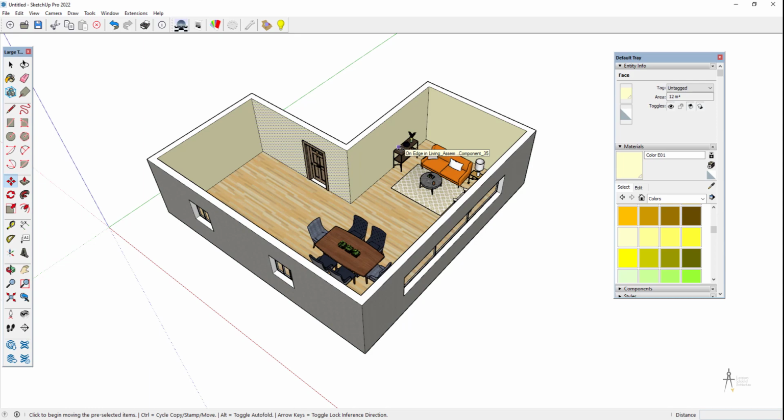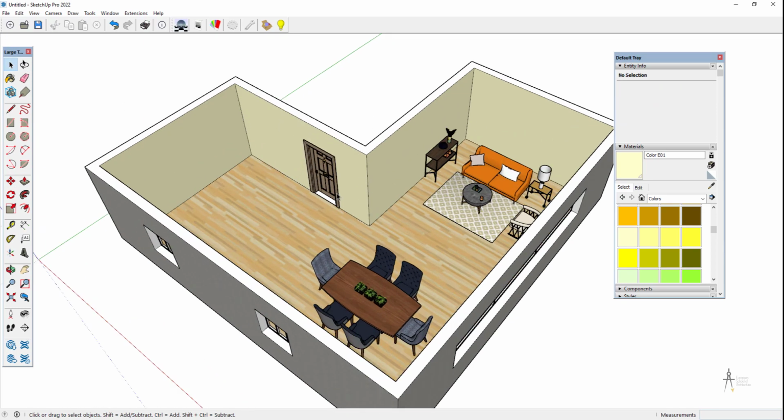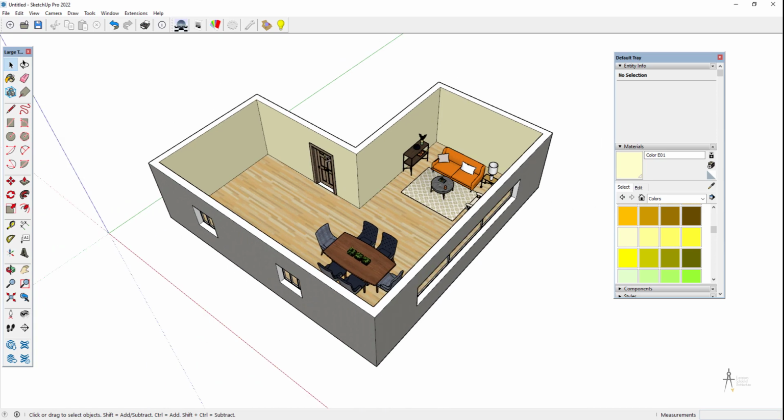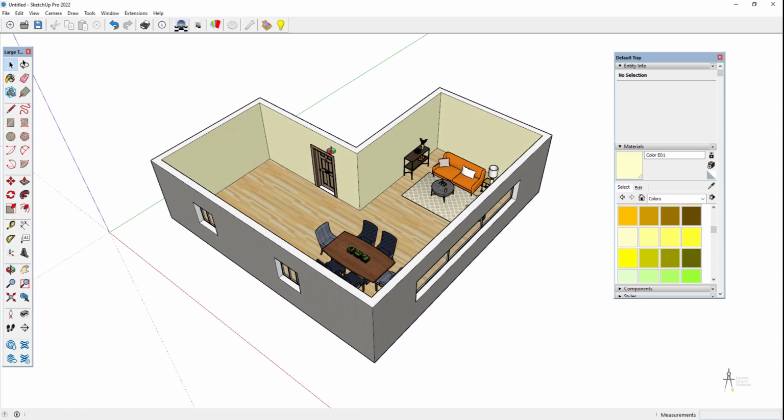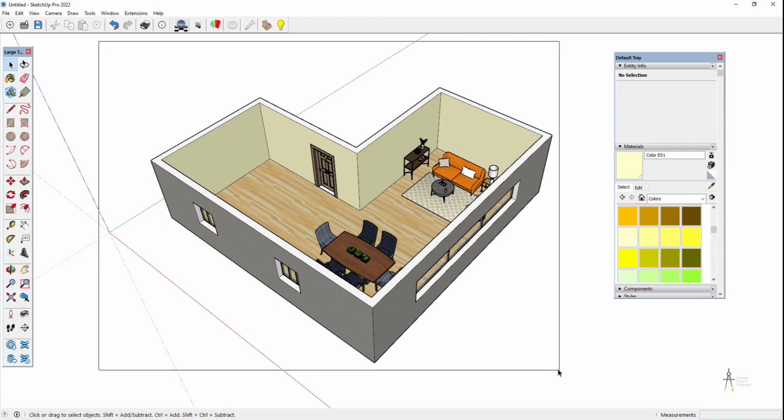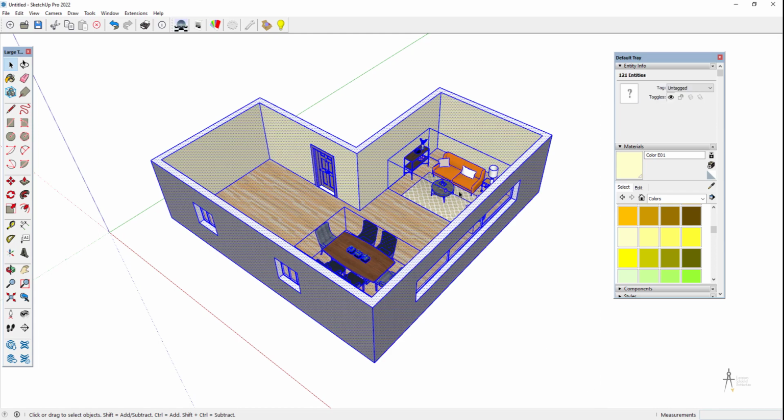And what we do at the studio when we design spaces in SketchUp is that we create components, okay? For example, component chair, component table, component floor, component walls, okay? And we create a hierarchy for these components, which we will see in other lessons, okay? And it's very important to be organized and well structured with this, as it is with layers in AutoCAD, for example. And this avoids possible inefficiencies like the ones we've seen.